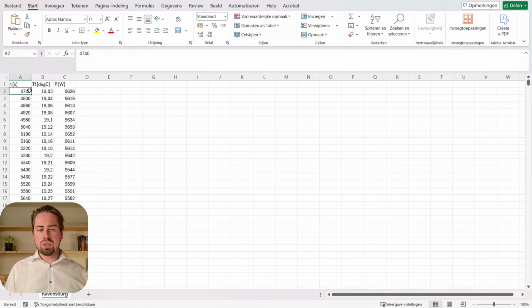Now, I want to draw the attention that in this case, the measurement does not start at 0. And that's what I said, that in these initial hours, the fluid or the system is not in a steady state, so it was cut away. And if it was not cut away, you can select in GHEtool at which line you actually want to start with the steady state, so where the graph was exactly linear in this semi-logarithmic plot. But in our case, it was already cut away.